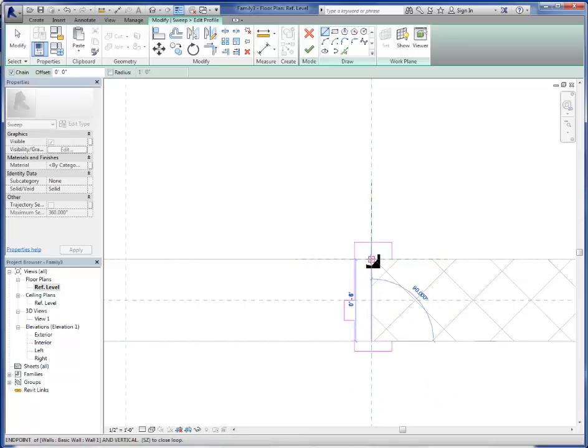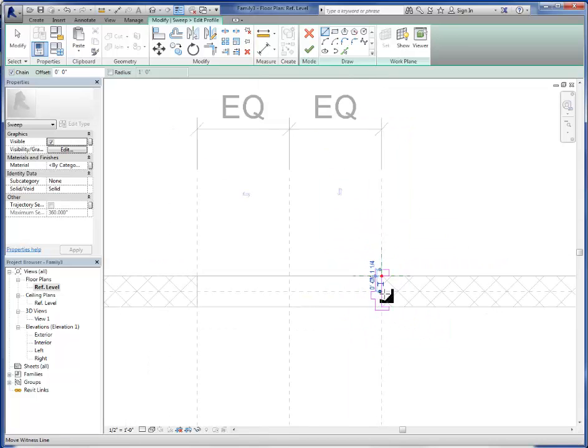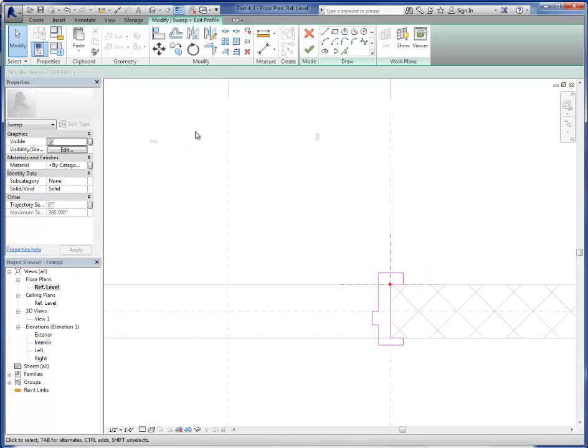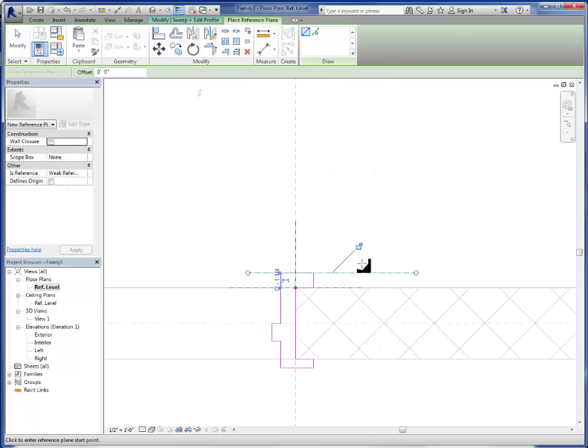And you'll note that I'm not actually removing anything from the wall here. The opening that's been generated, we're just going to accept that, and we're adding on to geometry, not actually reducing that. Okay. So then what we can do is we can come in here, and if we press RP, reference plane, we can start to draw reference planes on this.